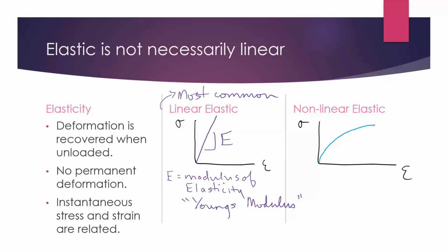And in this case, you still have a Young's modulus. You still have that value of elasticity, and Young's modulus in particular is what we refer to as that initial slope. So that initial slope has meaning for concrete, but very quickly as you go along the constitutive relationship, it starts changing slope. It's kind of more of an arc than a line.